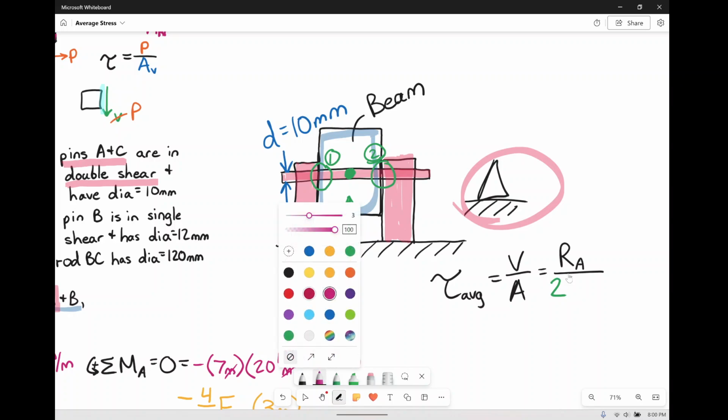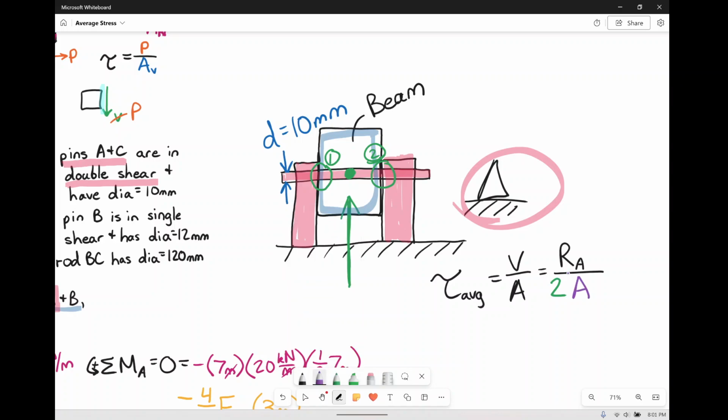And what is the area? We'll do it in purple. If this is a diameter 10, remember that the area of a rod is pi over 4 d squared. Because you know that for a circle it's pi r squared. R is the diameter divided by 2, so square that divided by 2 part, you get divided by 4, right? That's just basic manipulation of equations.